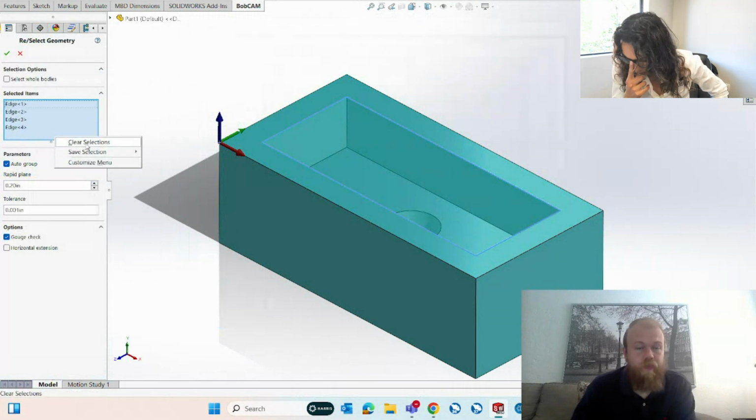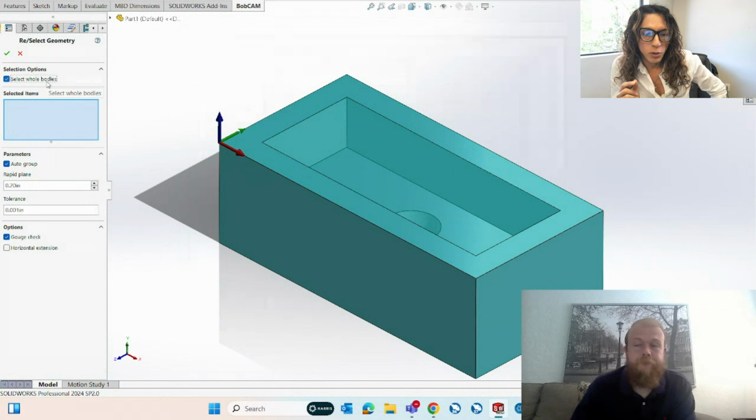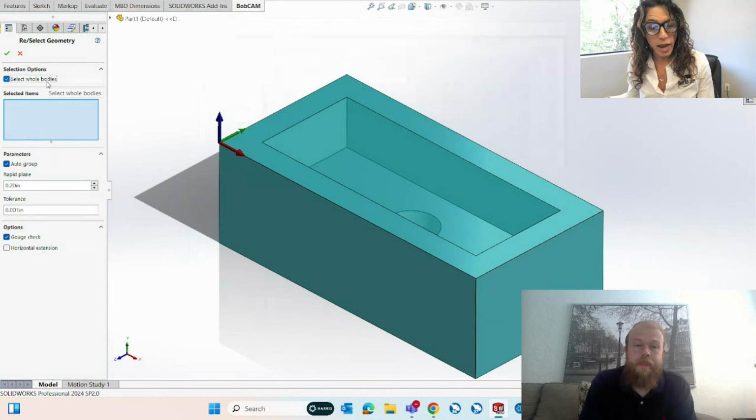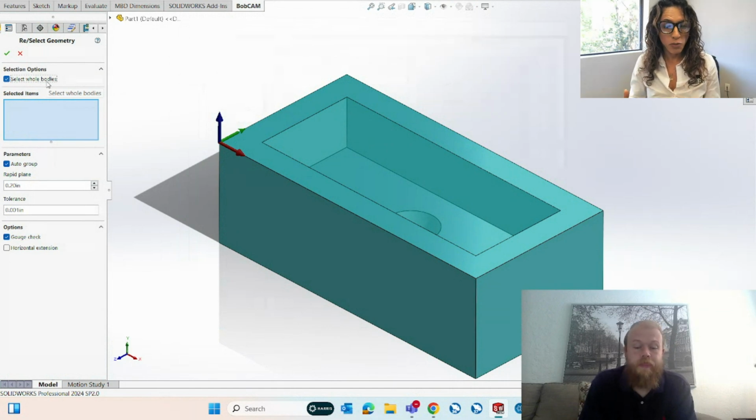And something else that is important, maybe you could go back into the CAD and show a little bit about it, because the point is to show SolidWorks and how we can add drilling operations. SolidWorks has a drilling library, so you can add your holes with specific properties. And now BobCAM for SolidWorks, something that it can do is read those properties to have them shown in our system, so it makes it easier.